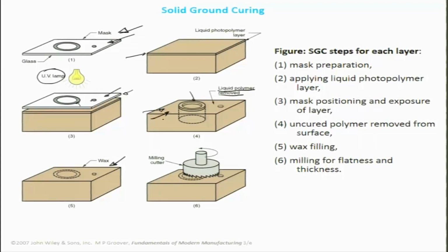So when you are coating this 3D feature which has been formulated on the top of the surface here with wax, the wax kind of embeds. Look at how this feature is getting embedded. The lines here are dotted, which shows that it's a hidden layer. The wax formulates a layer on the top. We can actually have a micromilling cutter which removes the wax to a sufficient extent so that it just starts exposing the small solid layer, maybe machining a few mils of the surface, which probably gets the system ready for the second step of exposure.